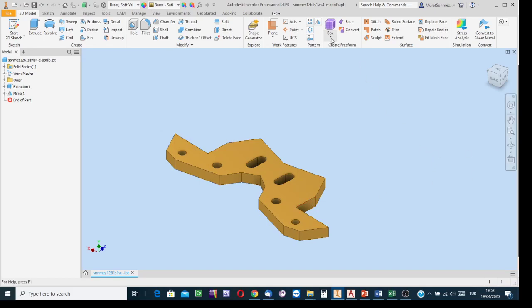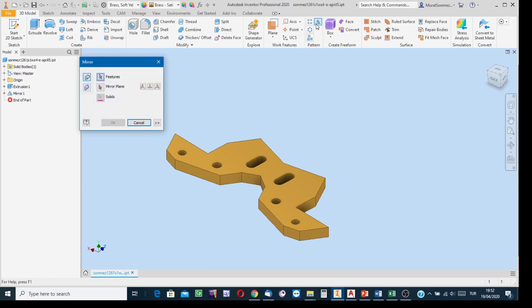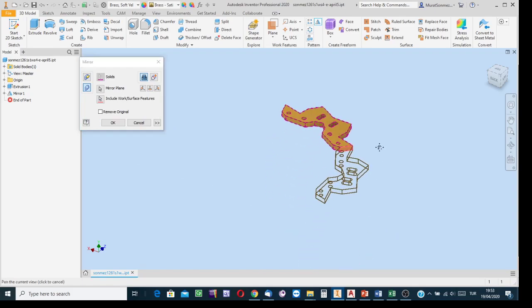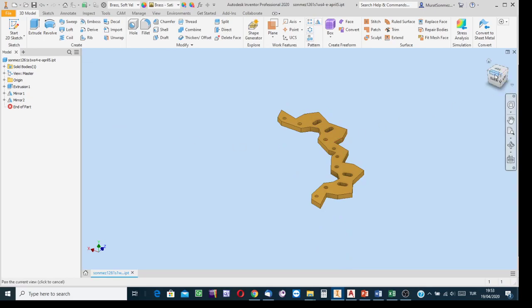OK. One more time, apply, click on this, start the process. Well, not the mirror copy of a feature, but gonna create the mirror copy of the entire of the body. Okay, great. Click on this button to say the mirror copy of the entire of the object, and then mirroring plane. Click on this and then indicate the mirroring plane. Here, create the copy with respect to this surface. So on and so forth. Yes, mirror copy.